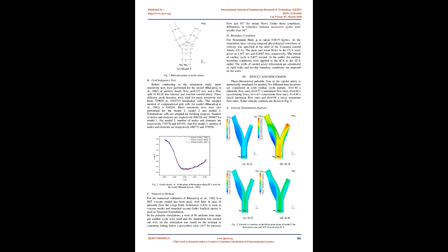2. Methodology. The continuity equation and Navier-Stokes equation are used to describe the blood flow through the carotid artery. These equations were solved using FLUENT, ANSYS 15. Continuity equation, 1. Navier-Stokes equation, 2. A. Model construction. 3 different carotid arterial models are investigated under the physiological flow condition. The model geometries are depicted in Fig. 1. The geometrical data of the models are derived from Bharadvahi et al.